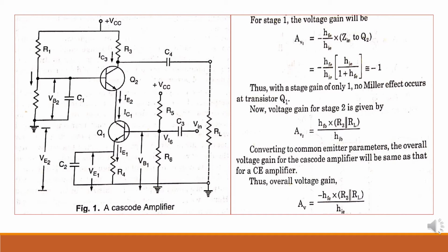Similarly, IE2 is approximately equal to IC2. So this means that the current IC2 is approximately equal to IE1. This current IC2 will remain constant irrespective of the value of the voltage appearing across VB2, as long as the collector voltage of Q1, that is VC1, remains large enough for the correct operation of the transistor Q1. As we have discussed earlier also, the input impedance of the transistor Q2 will constitute an AC load in the collector circuit of Q1.